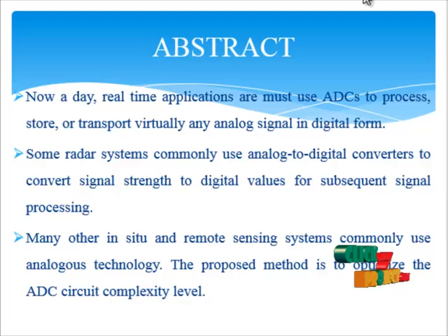Our ADC is measured under different input frequencies with a sampling rate of 250 MSPS, and it consumes 300 milliwatts from a 1.8 V supply. For the 30 MHz input, the measured SFDR and SNDR of the ADC are reported.